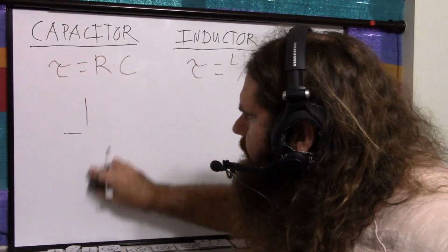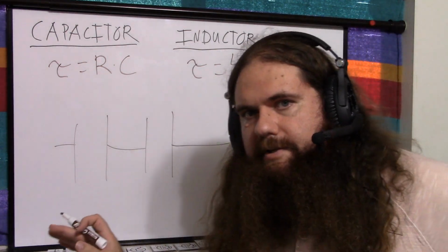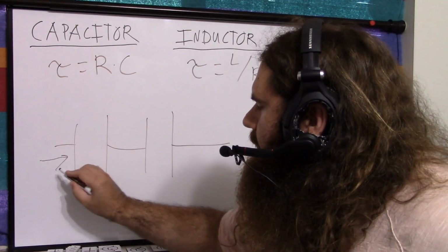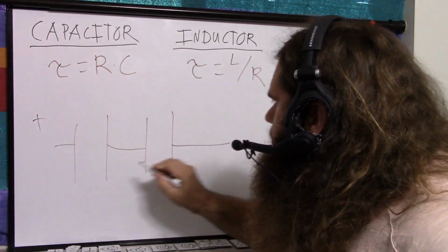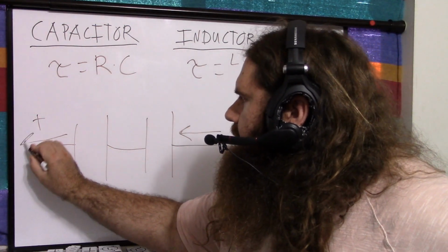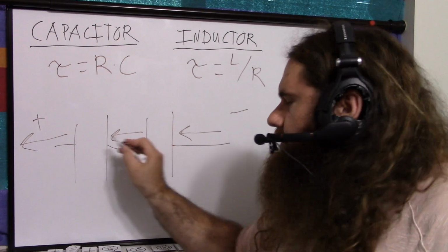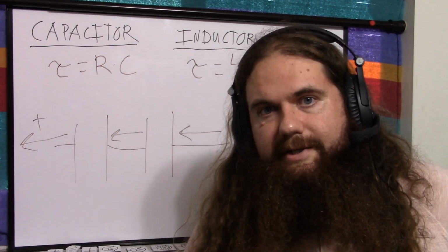So that would just increase the capacity very simply. Whereas if they're in series, you've got electrons being pushed. Let's say your voltage is like this, so negative voltage over here. So electrons are being pushed this way and they're being pulled this way, but in between them, they're being pushed from one to the other, and there's a complex interaction there, so it doesn't quite just add up.